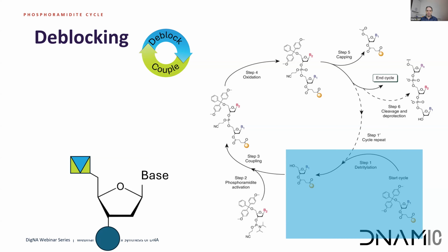You don't need to do both, because once you do one, the other one sort of follows. There are lots of other cycles involved in synthesis chemistry, but in the case of spatial control of deblocking, everything else is just done by flooding the surface. And in the case of spatial control of coupling, all the other reactions other than coupling are done just by flooding the surface with the appropriate solvents and reagents.